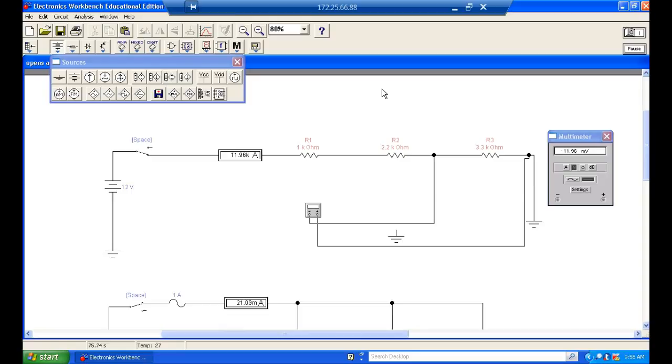Odds are it would not give up, not unless you took a jumper cable and put it across your battery. And then you need to say a little prayer, because your battery would get extremely hot real fast. It's got water in it. What does water do when it gets hot? Expands real fast. So when you short out a battery, a car battery could blow up on you. And that's not good, because not only do you have shrapnel heading at you, you got acid heading at you too, right? So please don't short out your car battery.